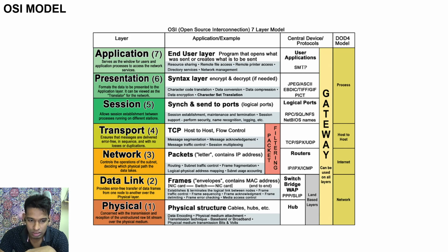And what does RS485 or RS232 say? It says that the voltage level has to be so and so. It says that you have to use so and so pairs of cables. You have to use a balanced signal, or in the case of an RS232, you have to use the unbalanced signal. You can use a 4 wire.